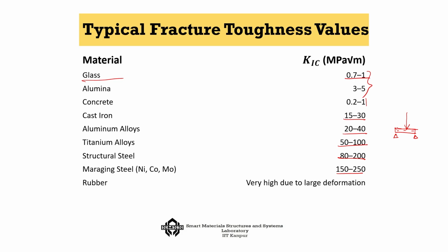So, it has iron and also a certain percentage of nickel, cobalt and molybdenum. In the process of annealing, we actually precipitate each one of these trace metals inside, and these precipitations harden it. So, it is called precipitation hardening.